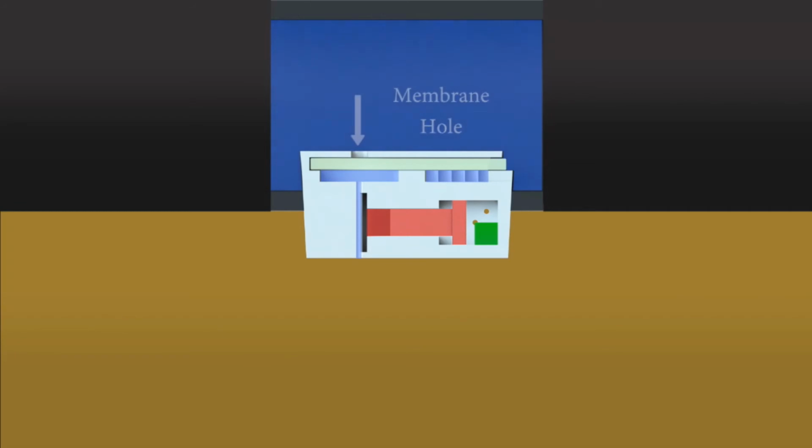A flexible membrane acts as the pressure regulator. As the pressure in the tube increases, the membrane flexes, gradually restricting the outlet. This allows it to maintain a certain flow rate for a range of pressures, making it pressure compensating.